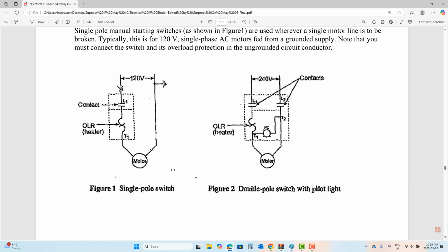I put one relay, which is a combination of a coil, which is represented by two C's put together back to back, and two lines, which is a contact. What are these two C's? Just like any overload device, what's the job of the overload? In the event of overload, get rid of the power. That's the whole beauty of having all these breakers on the panels.